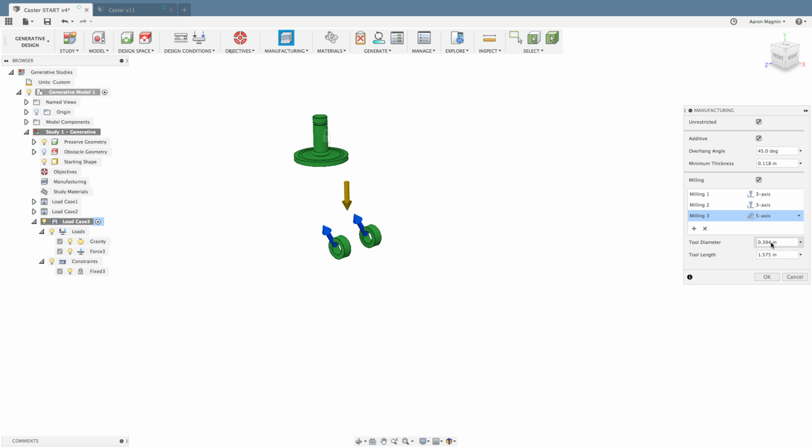So the other thing to consider when you're doing this is to determine things like the tool diameter. And what you're thinking about there is not your roughing tool, right? You're not thinking about your face mill. You're thinking about when you're going to finish this thing, what tool diameter is essentially the smallest that you'll be using. And this is something that you'll be able to define here. And we're looking at ways of improving definitions here and adding more abilities so that it's going to consider more information about your machines as you get into using this.